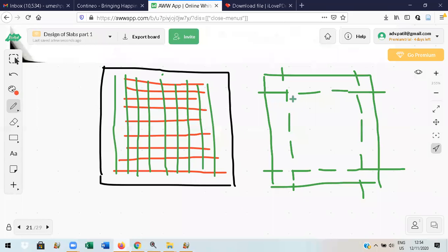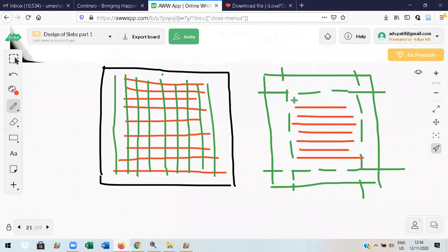So in the middle strip, whatever is there, we call it the middle strip. These are all imaginary lines divided with suitable dimensions. I'll give you that. So here you provide reinforcement in the shorter span like this. Whatever I have shown in red color is provided here. It means theoretically only in this middle strip reinforcement is required, because bending is maximum in this.